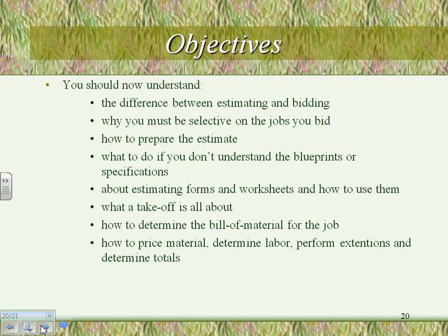Move into page 54. It's showing you the meeting room, with all the lights and receptacles in it, and they're doing the takeoff on these fixtures. Look at the legend and how many items of each one of these receptacles. I have receptacles at 20 amp, 125 volt. I have 9 of them. Can you guys see that? Insulated ground receptacle, I have 2.